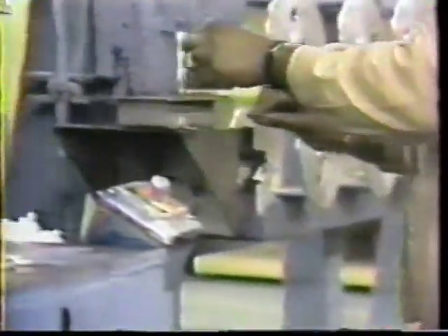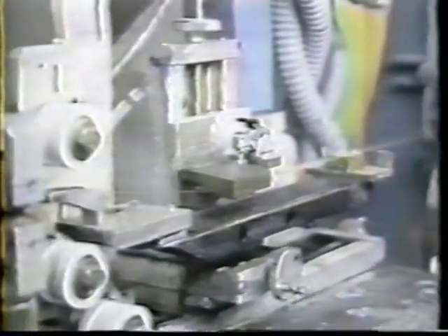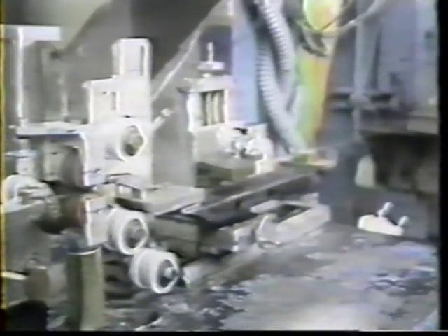The payout section may accommodate up to 12 spools of fiber selected from inventory. Under controlled tension, these are fed through a 12-position organizer, which keeps the fibers in proper orientation. At this point, the fibers also are color-coded for future identification. The fibers then pass through a geometric organizer, which positions the fibers into a flat, closely spaced arrangement.